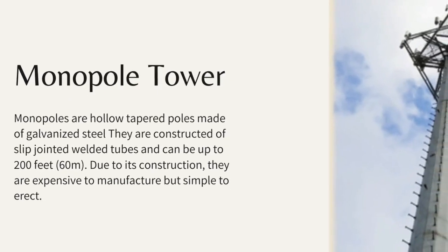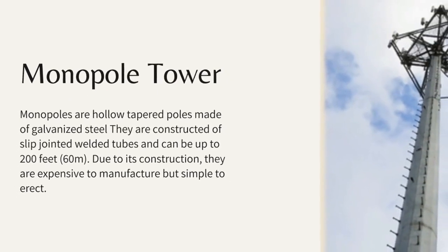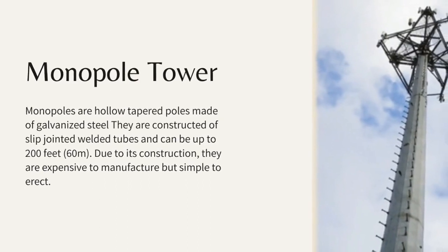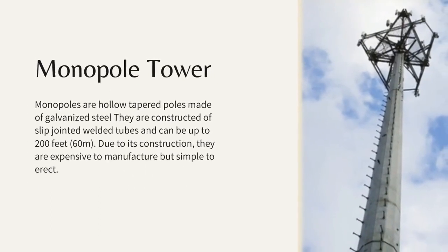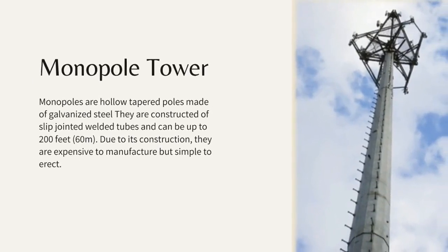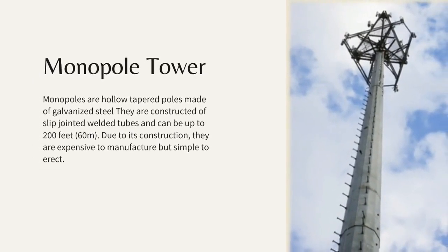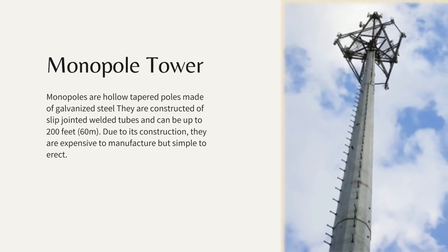It is a hollow tapered pole made of galvanized steel. They are constructed of slip-jointed welded tubes and can be up to 200 feet or 60 meters, and due to its construction, they are expensive to manufacture but simple to erect.